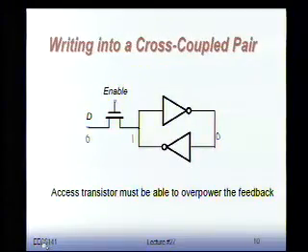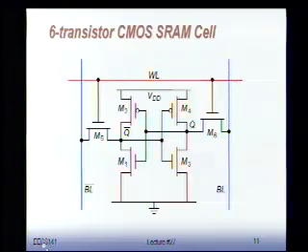And there's a couple of ways of doing this, but in SRAM, we have one particular way of addressing this. So this is what we did with our old strategy, right? It was a strategy we used for flip-flops. You say, I make one of those inverters a little bit weak, make the other one strong, and then I force one state in there. I overpower that weak inverter. Okay? That's one way, but it's very hard because it's asymmetrical. Okay? So in memory, we're going to do something different in SRAMs.